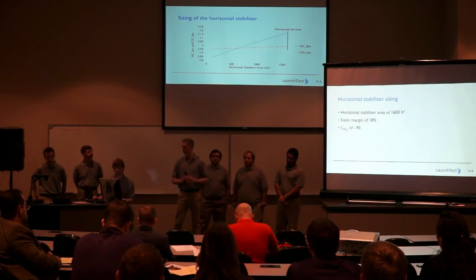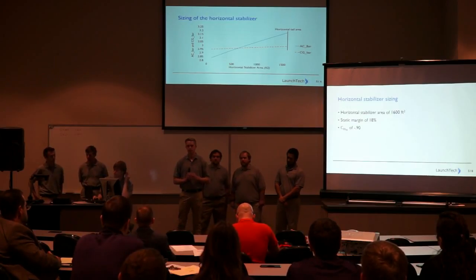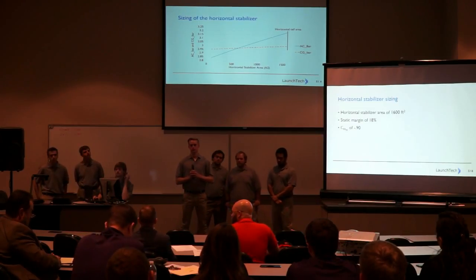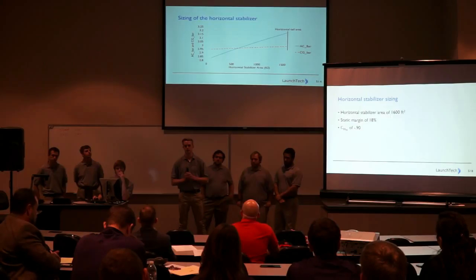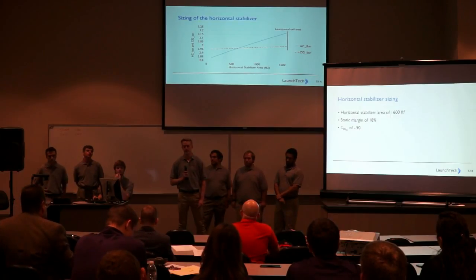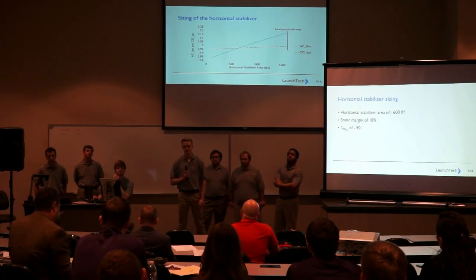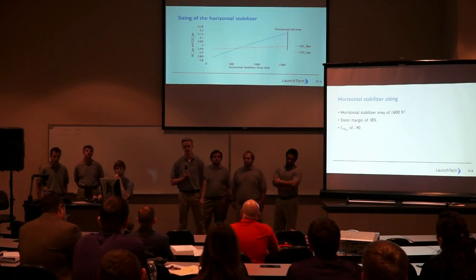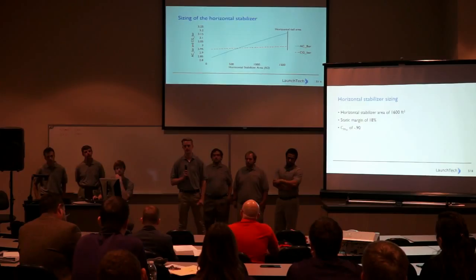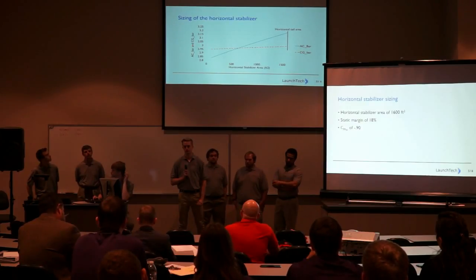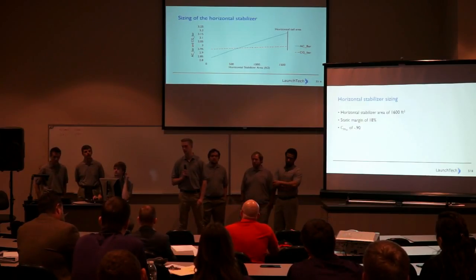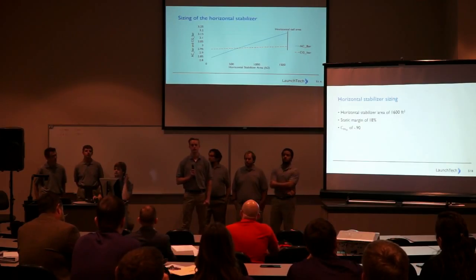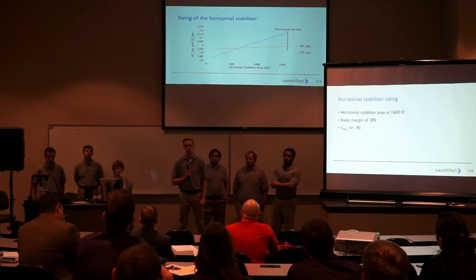So for stability control, I like the recommendation that you made to look into the wind tunnel analysis of having it deployed. I think that's a real good thing to look at. My concern was the sizing of the stabilizer and even your elevator. Would it be able to overcome the moment created from deploying the Ambassador?